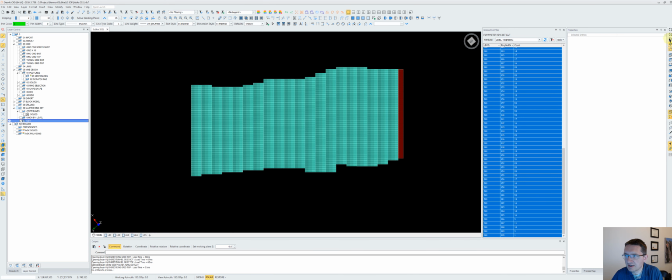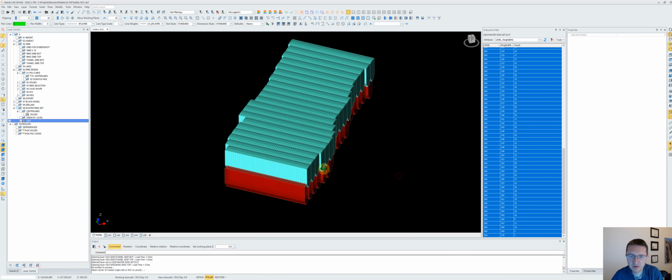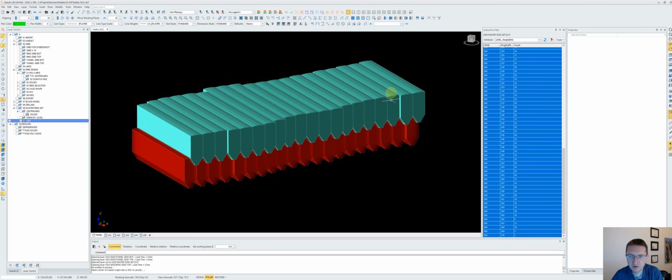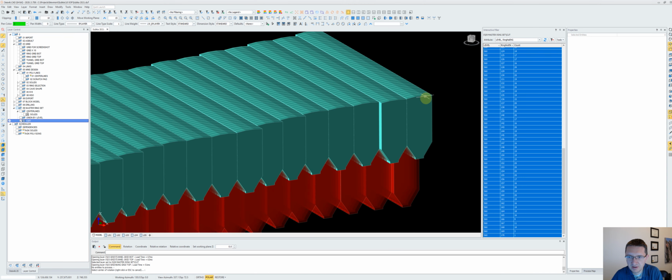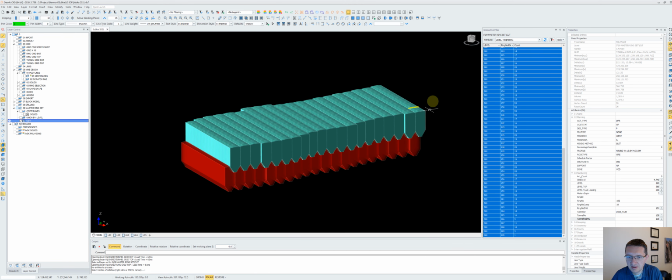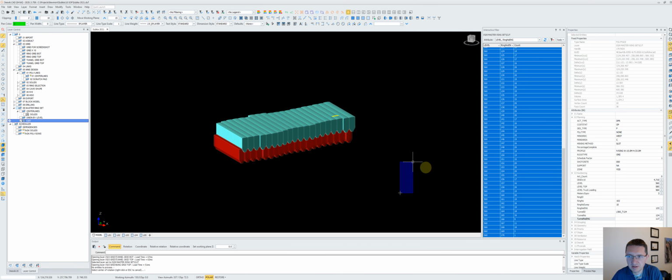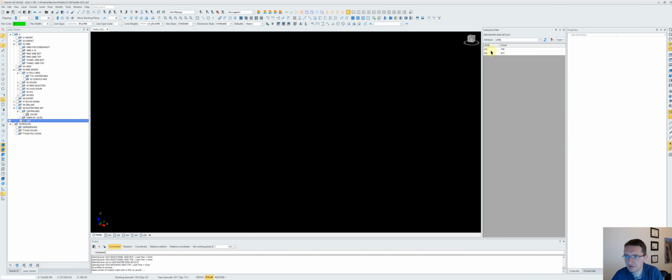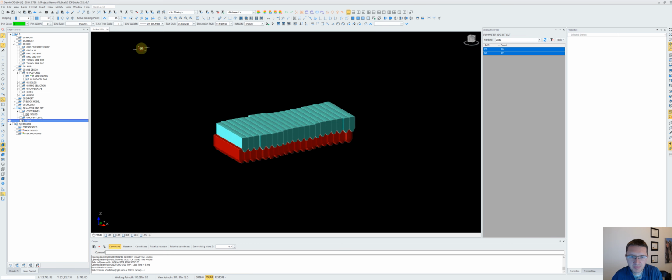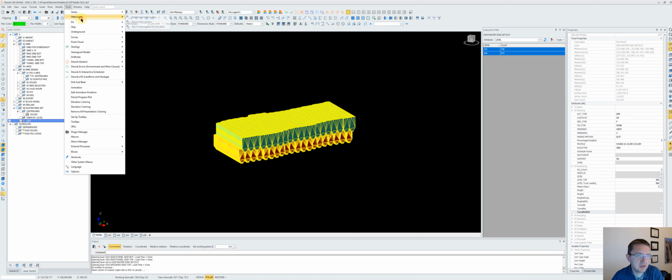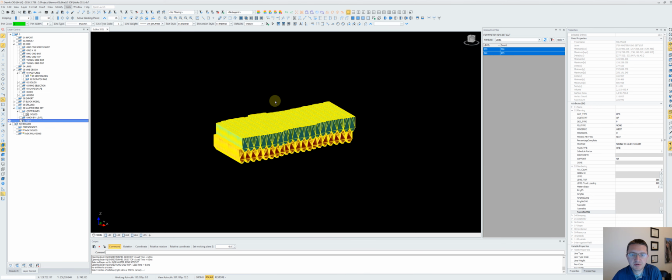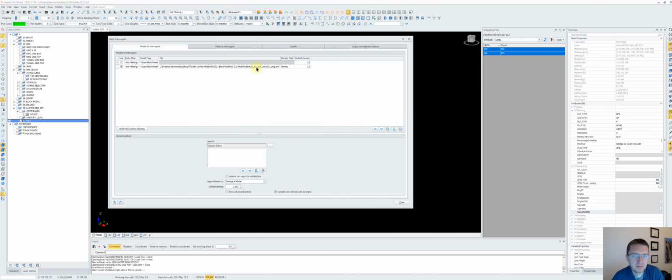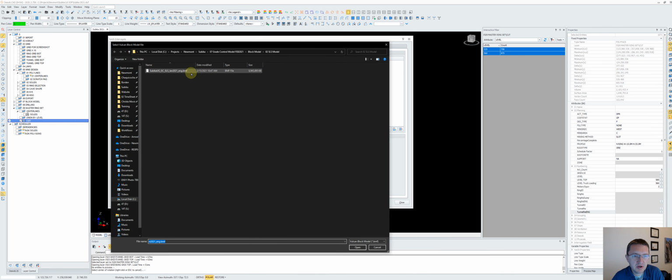And I think you get the idea. We need to have some solids. We need to be able to organize them in tunnels and in rings. For each one of these, this is the rings, and then each one of these is a different tunnel number, and now we can interrogate them. So I'm going to get rid of that and just have the levels. There we go. So select them all, go tools, interrogate, batch interrogation. We're going to make sure we got the right block model there.